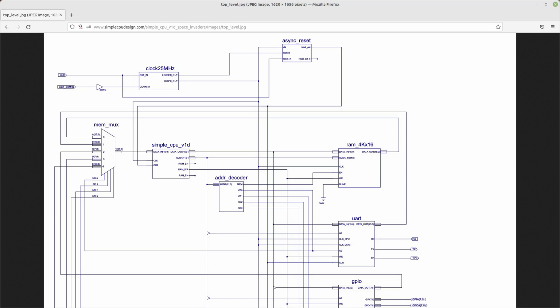In addition to that, to help simplify the process of writing games, I've implemented a number of high-level macros that will allow the user to draw graphics, define sprites, update the display, implement game logic, etc. So you don't have to always write the code at the assembly language level. That does come at a little cost, as there's quite a bit of cutting and pasting using macros, but it does speed up game development. And I've written a couple of small games now, Noughts and Crosses and a Space Invaders-like game, and 2K of space for game logic does seem reasonable.